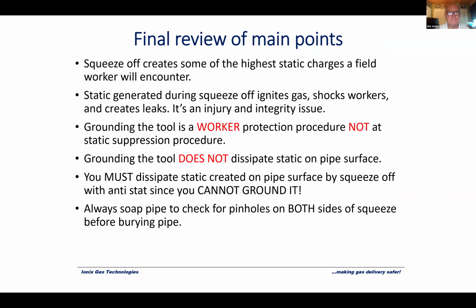So, Dirk, yes, James here. Is there a way to prevent pinhole leaks? No, unless you get rid of the static inside. We have customers that installed our internal static suppression because they were getting pinhole leaks from static, the normal transport of gas. And what we've seen is reductions in leaks of 88% in one case, where we reduce the static inside the system, the naturally occurring static, and we reduce pinhole leaks. So when you're doing squeeze off like that, unless you have a system like that, no, there's no way to prevent pinhole leaks, because you have to prevent the static buildup inside of the pipe. And there's really no way to do that unless you have interior static suppression.